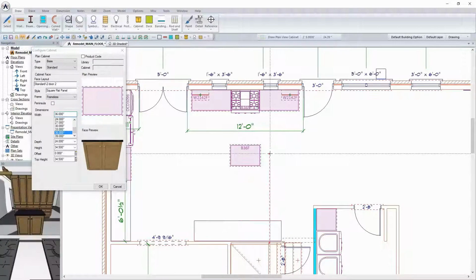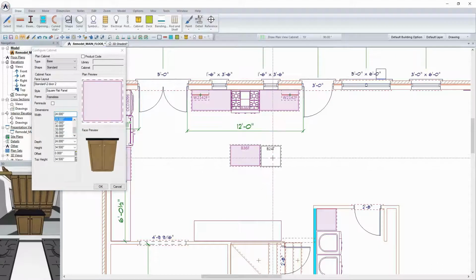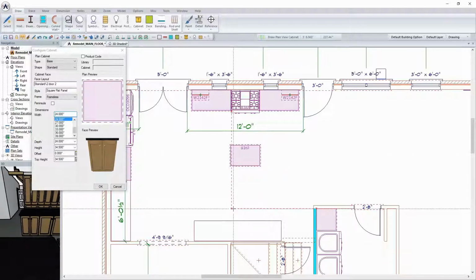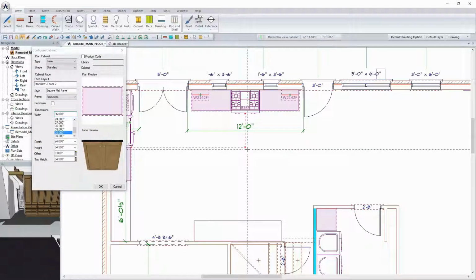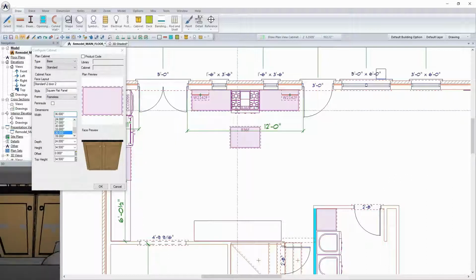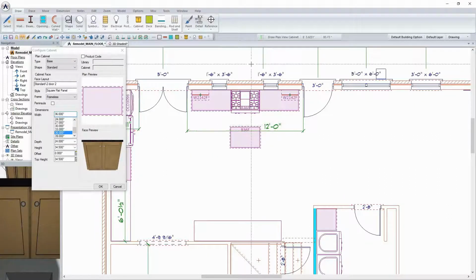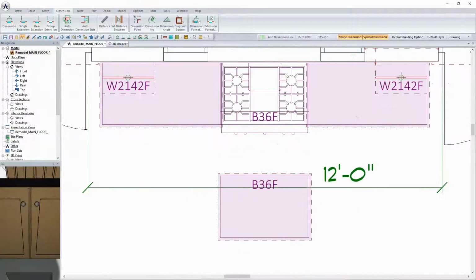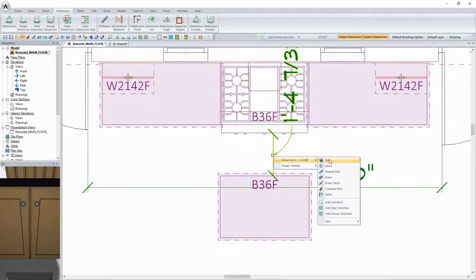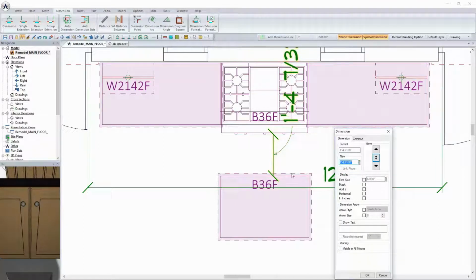Okay, and this base cabinet will be the one that holds the sink in it. We also know that beside that we're going to place the 24-inch. Just because I did it so fast, I want to take it back real quick. The projection snap feature allows me to find midpoints and endpoints of certain items. Because I have my snap feature on, it allows me to snap directly to the center line of this. I can also use the dimension feature, and with symbol dimension on, I'm going to draw the dimension from that gas range to the edge of the cabinet.